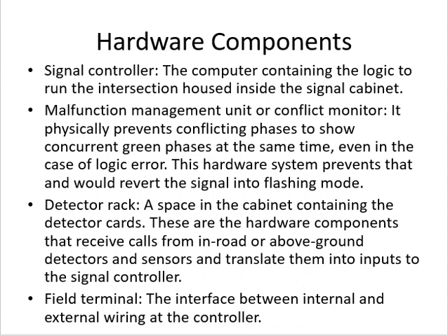Then we have a detector rack, which is a space in the cabinet. This rack has different cards, which we call detector cards. These are the hardware components that receive the call from the in-road or above-ground detector sensors and translate them as input to the signal controller.